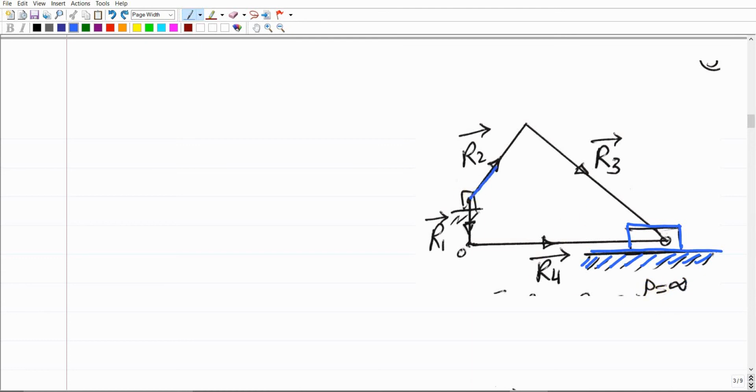And we do have one link, and we do have another link. This is the conventional slider crank mechanism, and there is R1, which should be like an offset distance. And we used to define R2, this is a position vector, there is another position vector over this link, and we have to set up R4 in the direction of motion of the slider, and this R4 should be going to the slider as we agreed before.